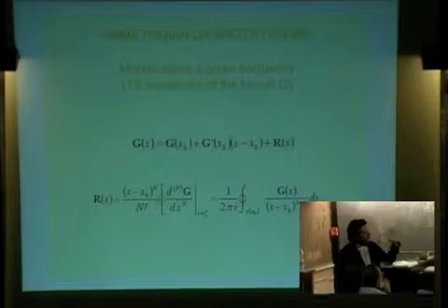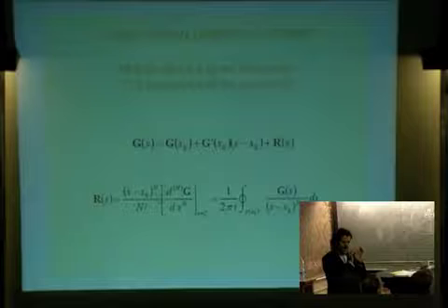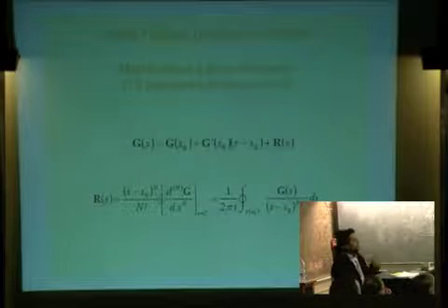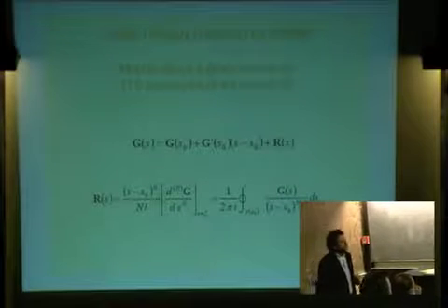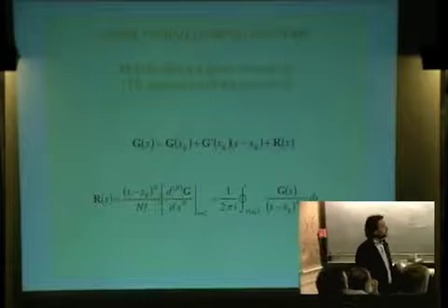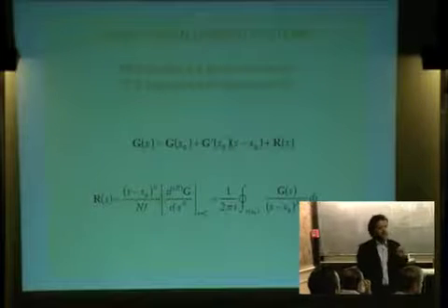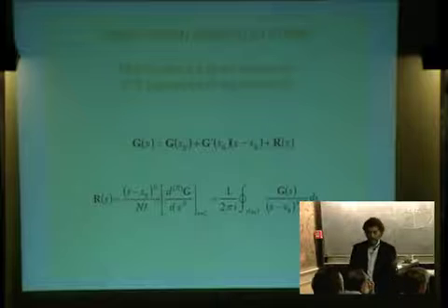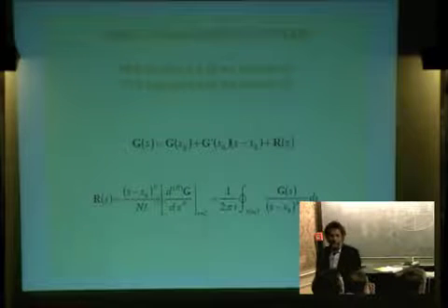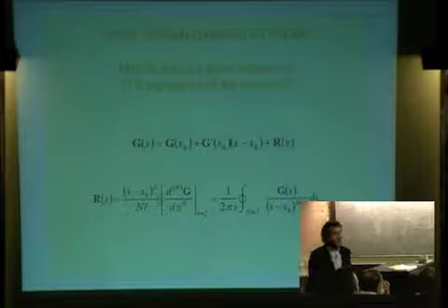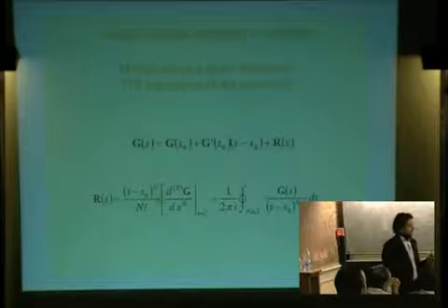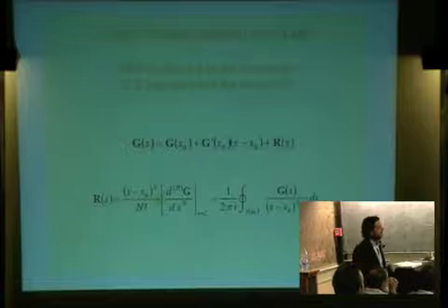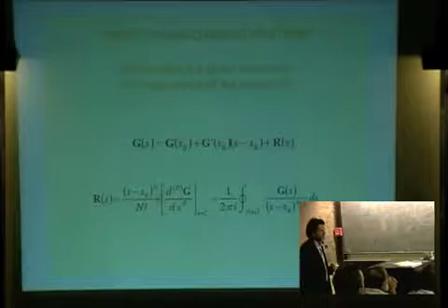I would like just to propose a first approach, to understand what characteristics come out from this analysis. The first point is, suppose that the motion of the system can be reasonably expressed using for G(S) just a linear expansion. G(S) is a complicated function of the frequency. Suppose now that we can use a first order Taylor series expansion.